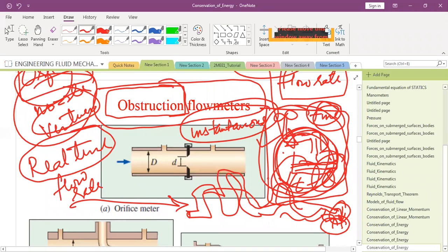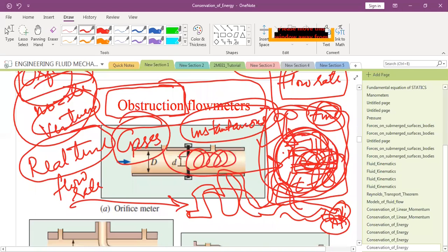Any other thing? What about gases? Can you use such a method in case of gases? No sir. There will be difficulty because the compressibility effect will be there. There will be different pressure in the tank and different pressure in the pipe, so the measurement you have taken might differ. If you want to take the same measurement, you will have to maintain the same pressure in the tank as was in the pipe.